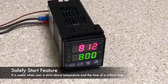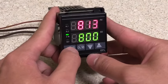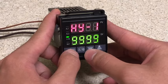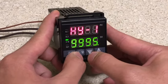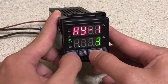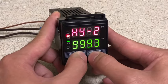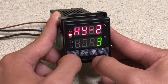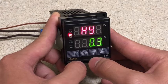Now I want to activate the safety start feature on my PID. So I'm going to go into my parameter settings mode. Making HY1 3. Making HY2 3. And keeping HY as the default setting, or 0.3.